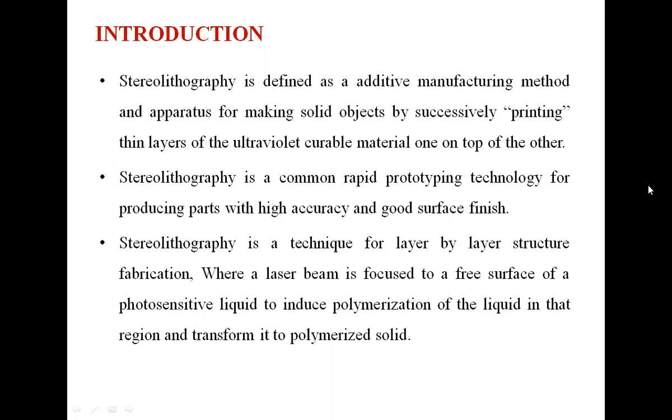The laser beam is focused on the free surface of the photosensitive liquid. We use the photosensitive liquid as a material and a laser beam, and the laser beam is focused on this photosensitive liquid to induce polymerization and convert it to a polymerized solid. The photosensitive liquid is exposed to the laser beam; after the focusing of the laser beam, it is converted from liquid to a solid form, that is, a polymerized solid form.